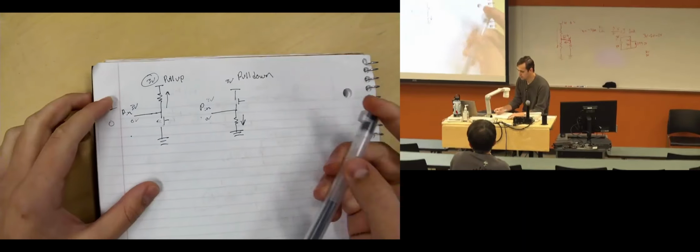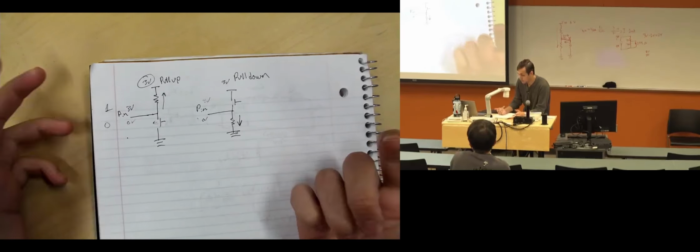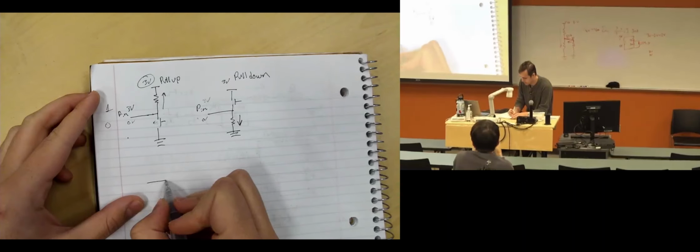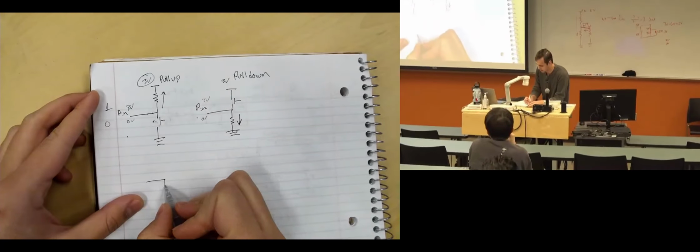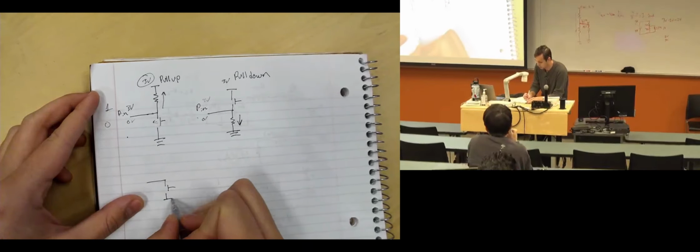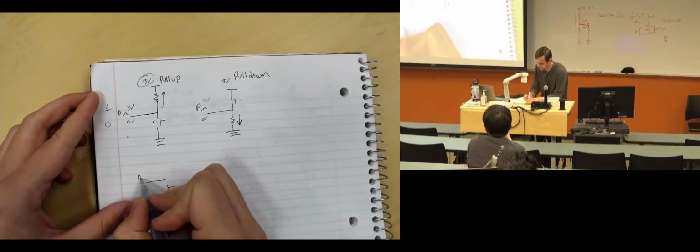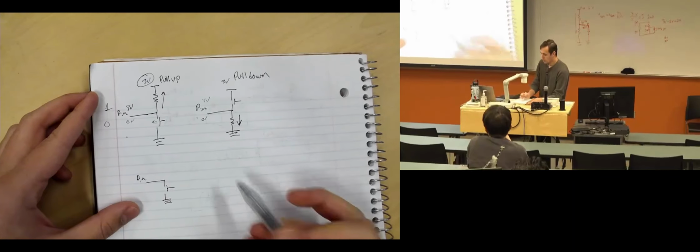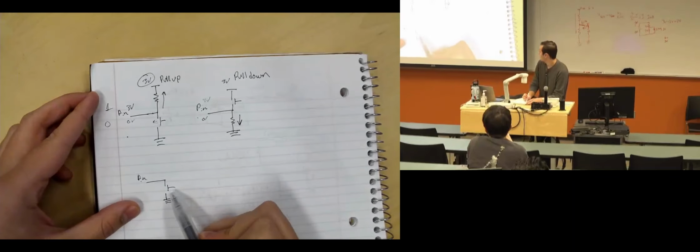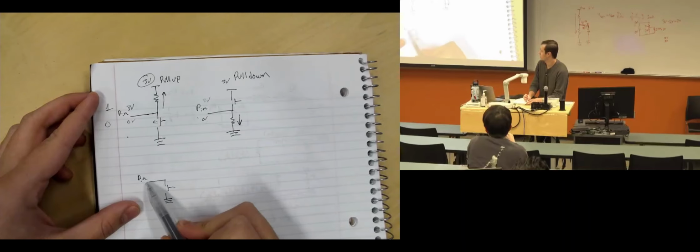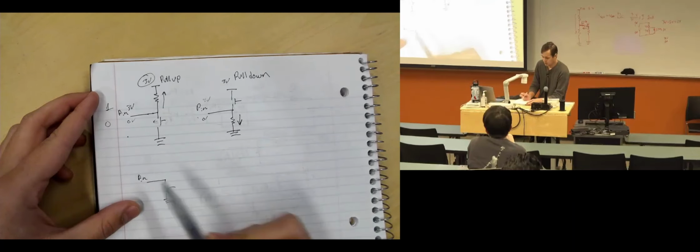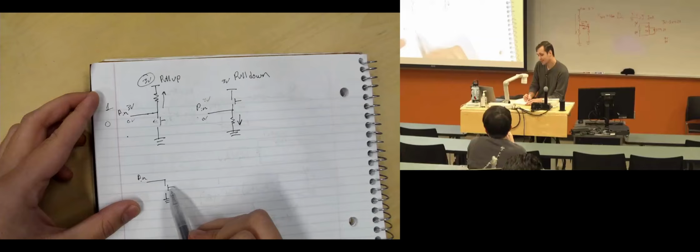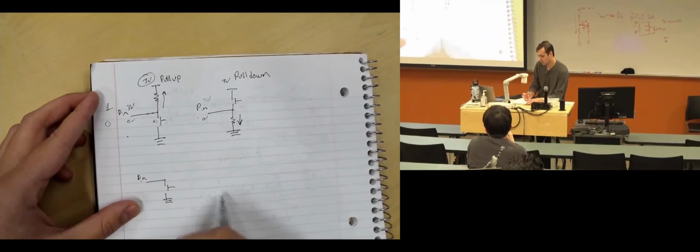I think we went over this a little bit in lab, but the reason we need these, right? Let's say we took the pull-up circuit and we just didn't have a pull-up resistor, right? When this button is pressed, we'll get 0 volts here, right? That's what we determined. When the button is pressed and then let go, what's the voltage on the pin?